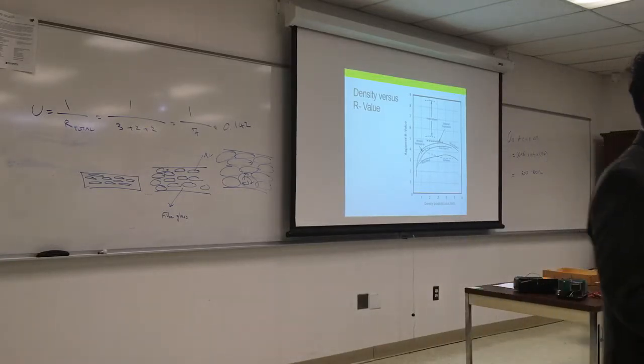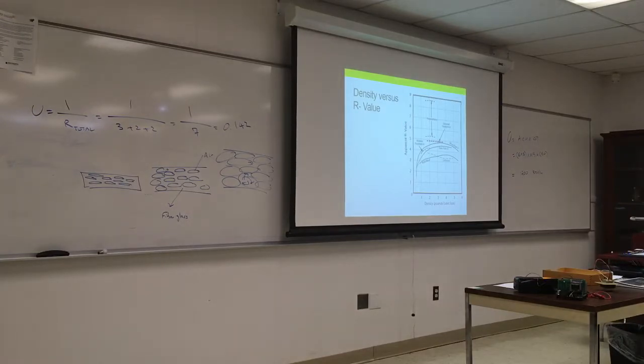What are some of the good insulators around us? Foam, polyethylene, denim? Denim is cotton. Cotton is not a really good insulator. Even though your jeans are very thick, they feel cool. Why? Cotton breathes better. Ceramic is actually not a good insulator. Solids. Rubber is good. Polymers are good. Asbestos is really great and natural and cheap. But the problem with asbestos is when it becomes airborne, it causes cancer.